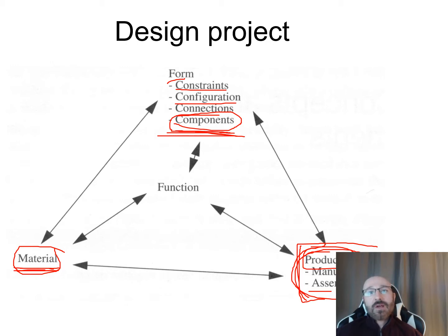But again, maybe it's a small, teeny little buckle, and there's a ton of individual parts within that. So all of a sudden, we might be able to do the molding for the lever arm of the buckle, but for the stainless steel base of the buckle, we need to do some type of CNC machining. Then there are springs in there for the assembly process that are going to take manual assembly, and there's not an automated process for that. So we're going back and forth between what materials we're selecting, what the components are, what the configurations of those components are, and our production methods, and we want to make sure that everything functions correctly.